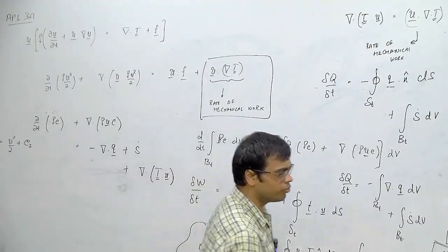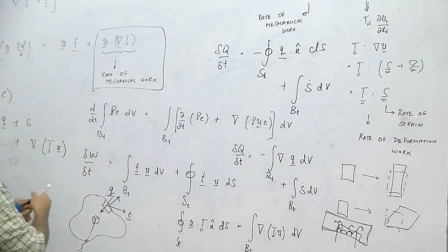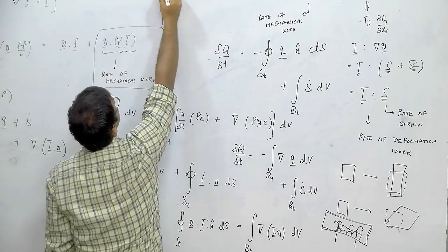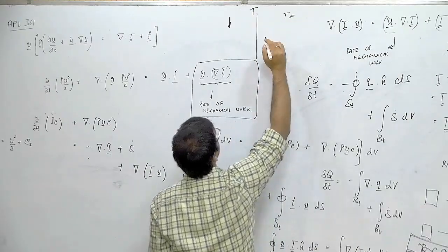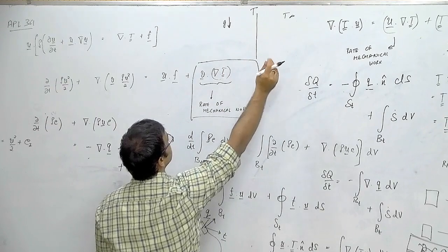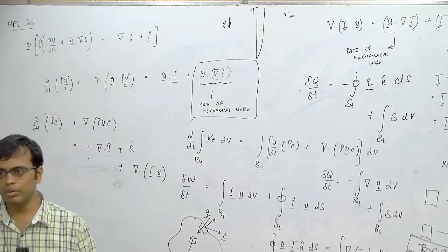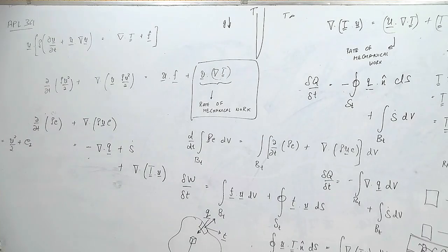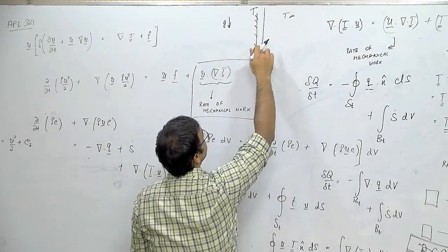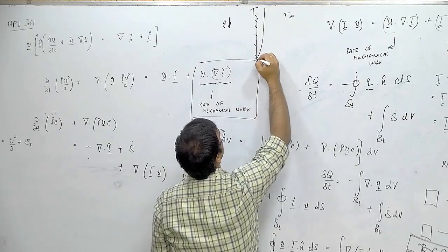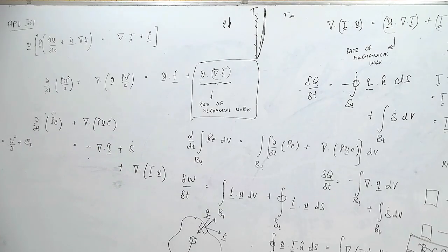So as we move forward, we will try to look at what is known as a convective boundary layer. So let us say you have a heated plate. Okay, this plate is at temperature T and surroundings are at temperature T infinity. There is gravity in the system. We will formulate the equations for a natural convection boundary layer in this. Okay, we will formulate these equations. We'll show that you can solve them somehow. Okay, and in this basically what we are interested in is solving the details of the flow due to external heating.